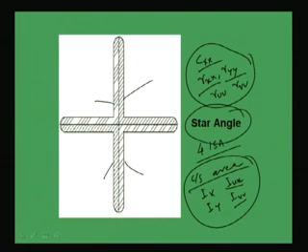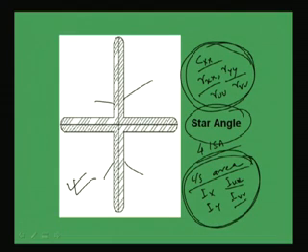Now the difficulty is for built up section we have to calculate all those properties. When a designer is trying to design a built up section, first they have to choose some sort of combination, then they have to find out the equivalent properties of the section. Then what will they do? Then they will find out whether the design is okay or not. If it is not okay, again they have to change and make it. Or if it is over designed, then again they have to reduce the size and make it. So it is a tedious job. It's an iterative job and it is a tedious job to make a suitable section.